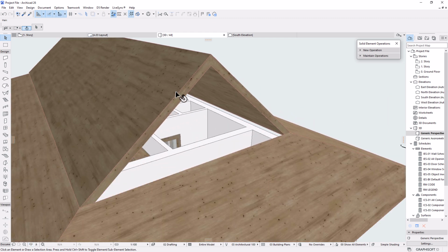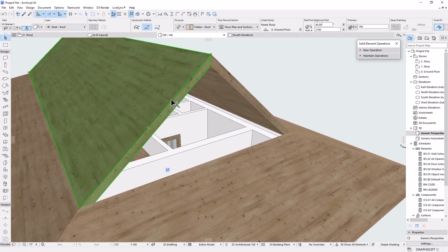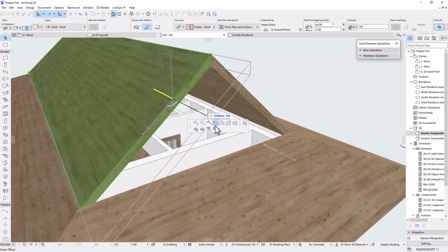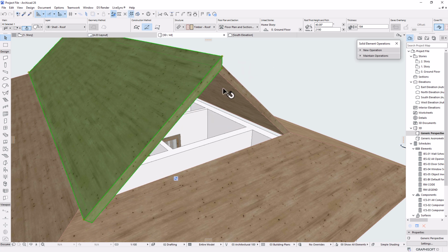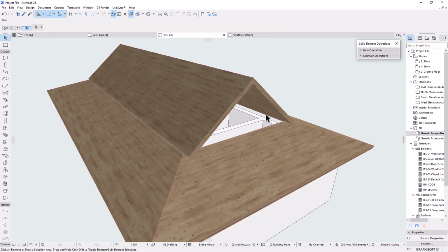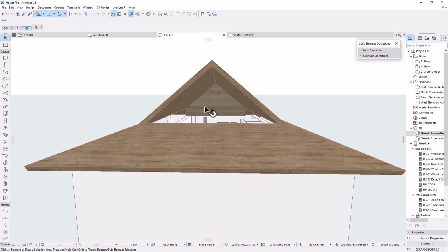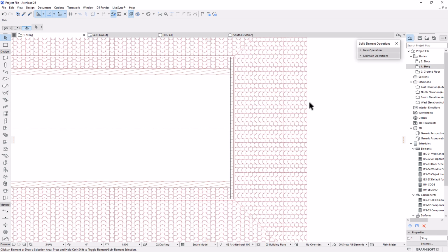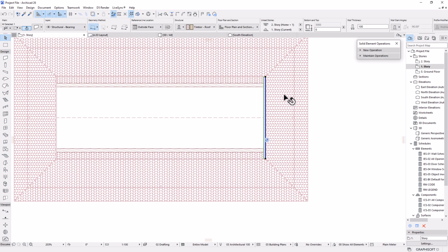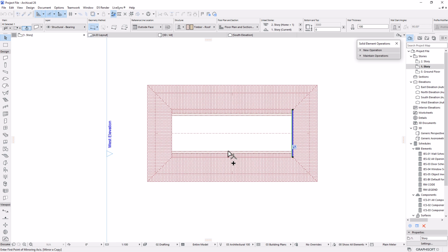Let's come here and then select the element, pick the edge, and make sure the offset edge is active, and hit 300. Enter. Do the same to the other one. This one we could just reference with the first one, just like this. So we need to mirror a copy of the wall that is from that side. So I'm going to go back to the ground floor or to the plane view, select the wall, Control Shift M to activate mirroring a copy.